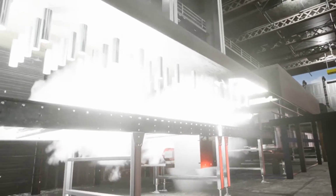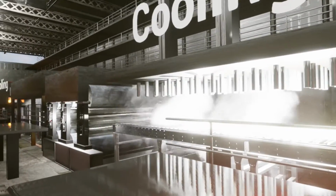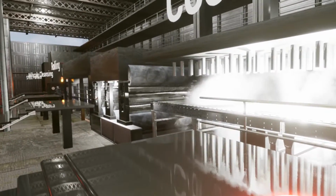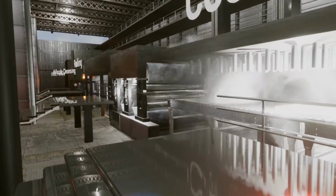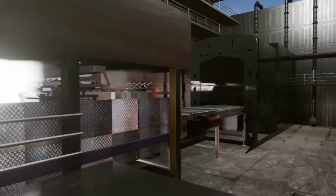If the oxide layer remains on the material during rolling, the layer risks being rolled into the steel material, adversely affecting the surface quality of the final product. The material must undergo a mill scale cleansing before rolling. In order to clean the surface, water is sprayed at very high pressures, around 160 bar.